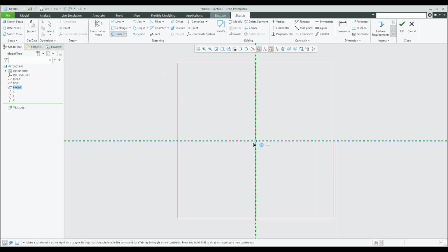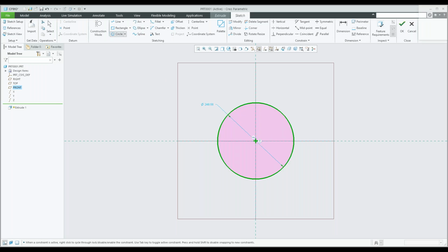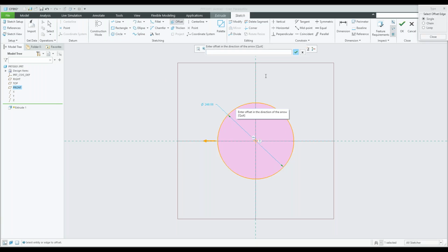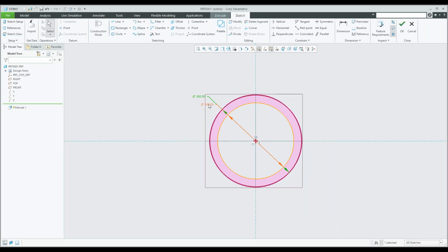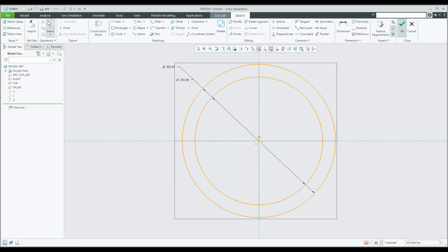So all you need to do is add the circle and then give it the offset you want. There you go. You want to change the values, I guess this is the spot to do it. It's going to make sense. So there's our flange. So we've input a circle and 2 dimensions.